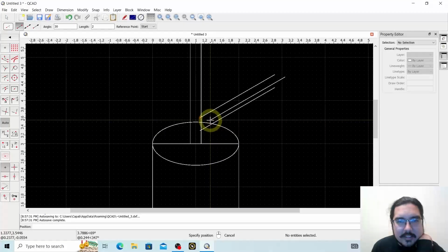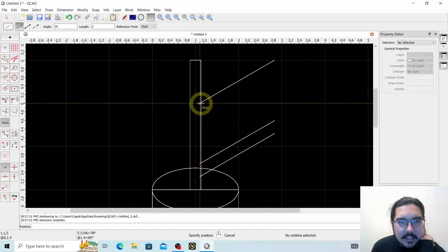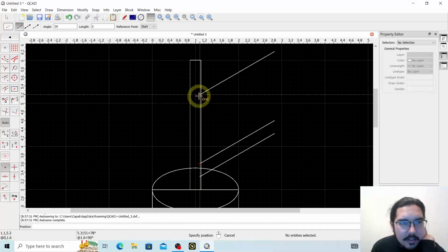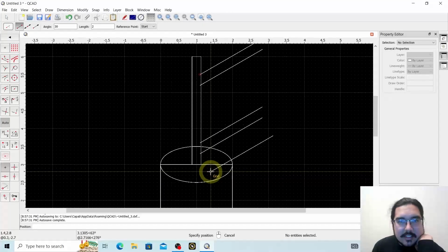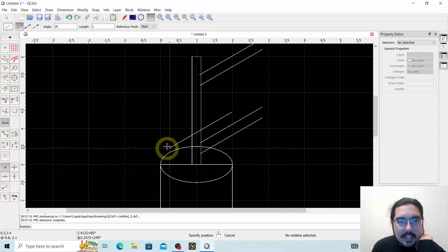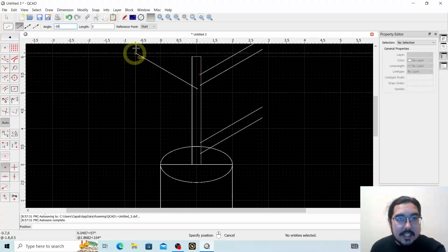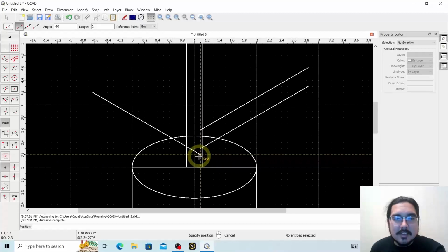Alright, so I've put 2 lines there, and we're going to come up closer to the end, and let's go with 5. Let's take this from the 5 line here. So I'm referencing this number on the far right hand side, and let's go with 5.2 to 5.5, and now we have all those lines there. Great. Now we want to extend it out on the other side. I'm going to go ahead and set this to negative 30 degrees here, and change it from start to end so that I can reference in the middle in the same manner here.